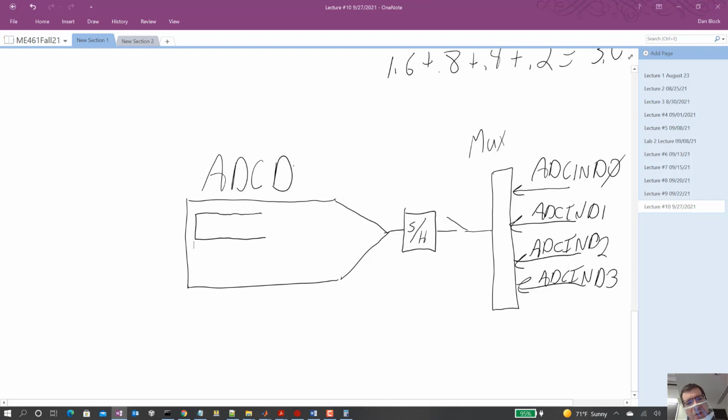It's just internal. But there is a DAC inside this, a 12-bit DAC, just like the DAC I just showed you, that can create a voltage between 0 and 3 volts. And then there's the ADC value register, ADC value. And yeah, it's got 12 bits again.